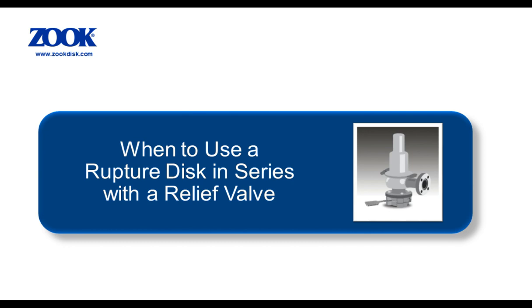This is a very common application where a rupture disc is used in series with a relief valve. In this case, the disc is placed immediately upstream of the valve, in essence isolating and protecting the valve from the process. The inexpensive rupture disc is the only part exposed to the process until an actual overpressure occurs. This is extremely advantageous in highly corrosive applications, combining the advantages of a fast-acting, leak-tight rupture disc below and the reclosing functionality of the valve above. Depending on the disc model, the valve can also be tested in situ without the need for removal, saving significant downtime and cost.